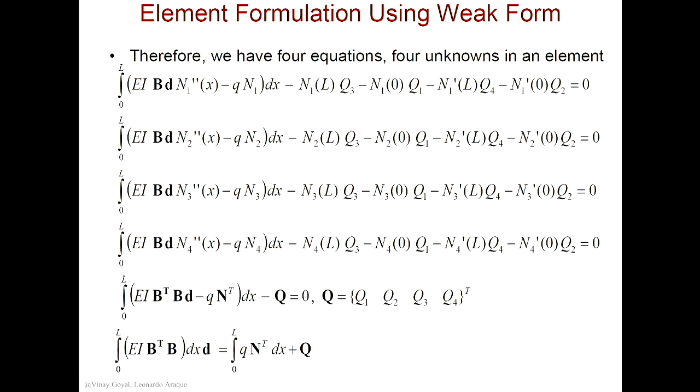That's basically it. That's my element formulation for the beam, right there. And the D does not depend on dx, so I'll bring it outside. And this is my stiffness matrix right here. And this is my force vector. This is due to distributed forces, and this is due to concentrated forces, or internal. These are internal loads, by the way, at this point in time.